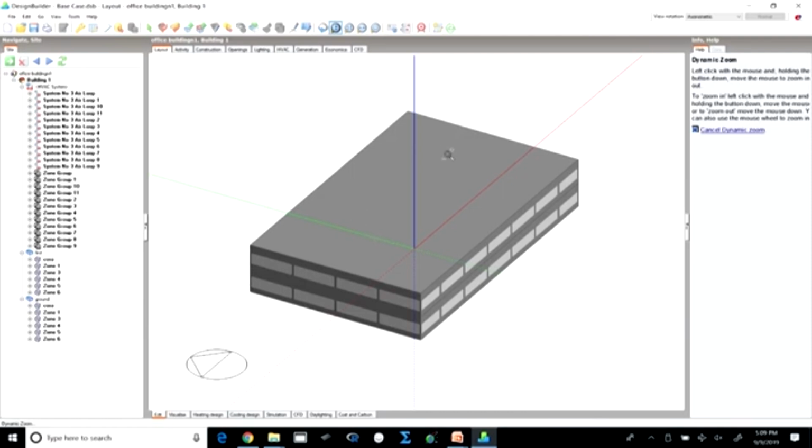So, north, and then north on the shorter side, north on the longer side, and the other one. In this case, since the building is rectilinear, it will not make much of a difference and we can average out of 2 as well because it is uniform. However, if we are doing an irregular building, then we simulate it for all 4 major orientations and then calculate the average overall electricity consumption, energy consumption for the building by taking an average of the 4 base case buildings.